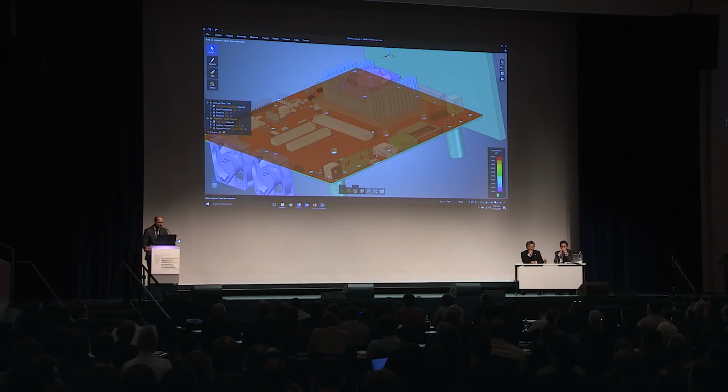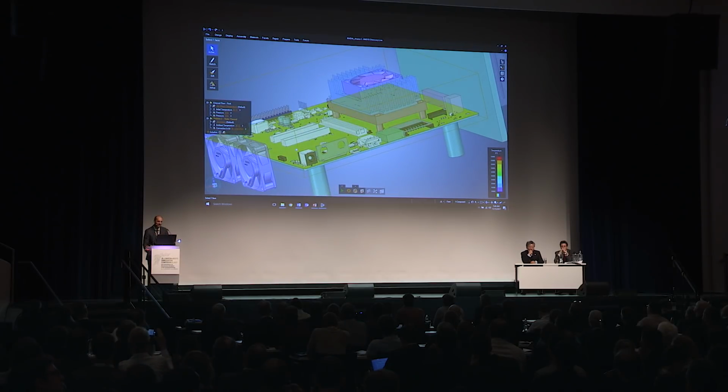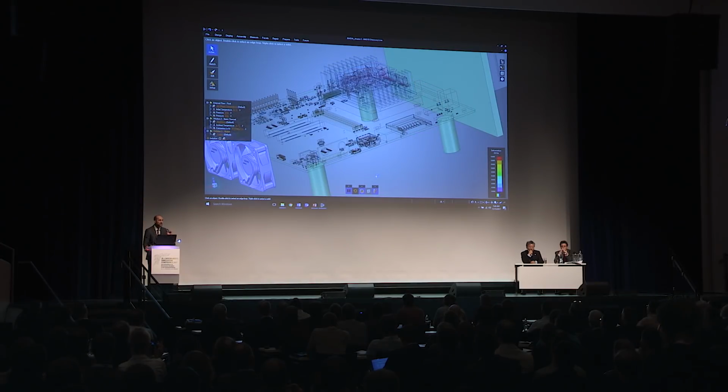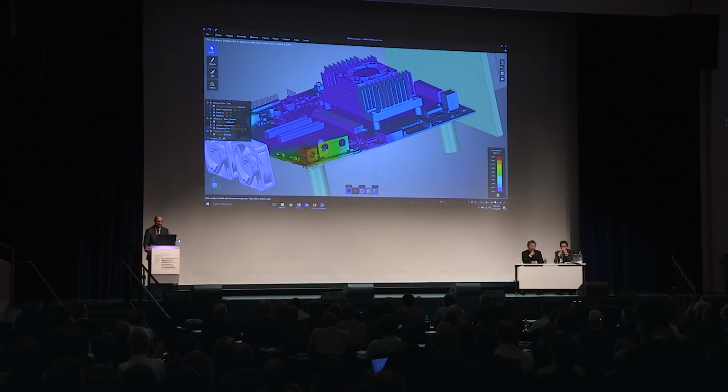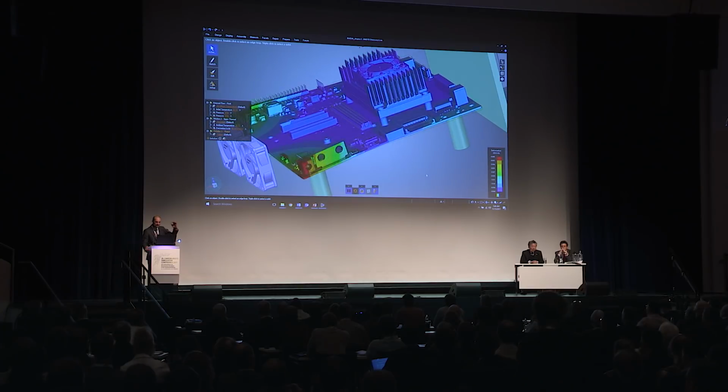So to start, let's grab everything that's in this setup of this board, including the heatsink, and let's run a modal solution on it. All I have to do is pick from one of 4 included types of physics, specify a material. I can, of course, assign multiple materials for different elements inside here if I really like. And that's it. All I have to do is hit play. What you're now viewing live is a modal result. You can even see it converging in real time to your right.